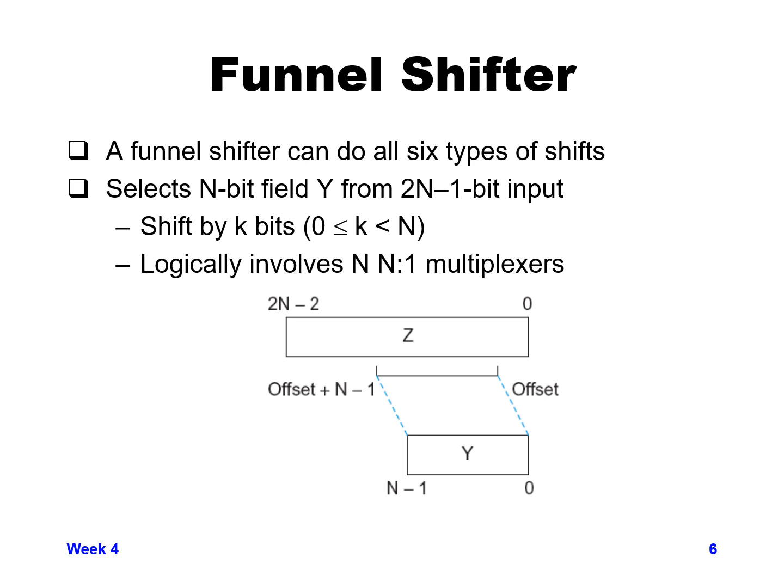number, which in this case shown in the diagram below is the number y, or the data value y, that has n bits in it, and you create a new value z that's 2n minus 1 bits long, and you have it inserted in z in a specific number of bits that's shifted from the right hand side, so you don't have bit 0 going in bit 0, you have it shifted by a certain offset, and so you have an offset on the right of it, and then some additional bits that make up the rest of the 2n minus 1 total number of bits on the right hand side of your original value y, kind of in the middle, or not necessarily centered, but in the middle of the z larger number of bits.